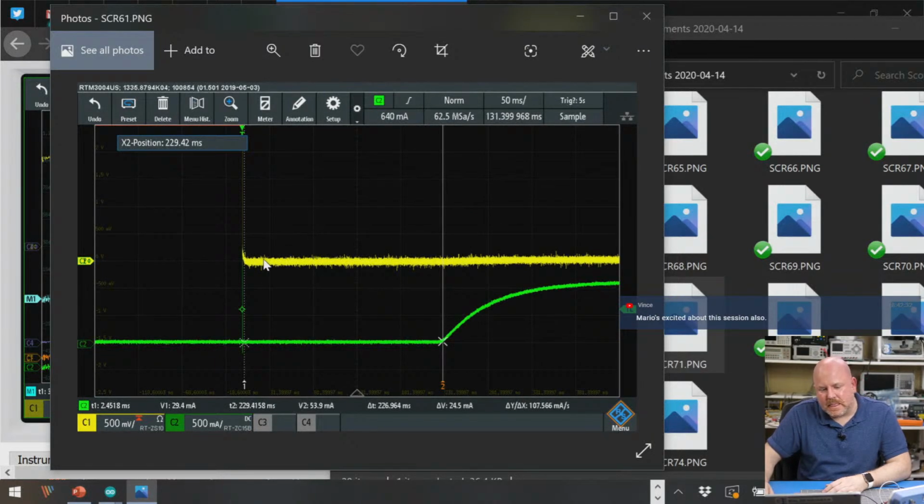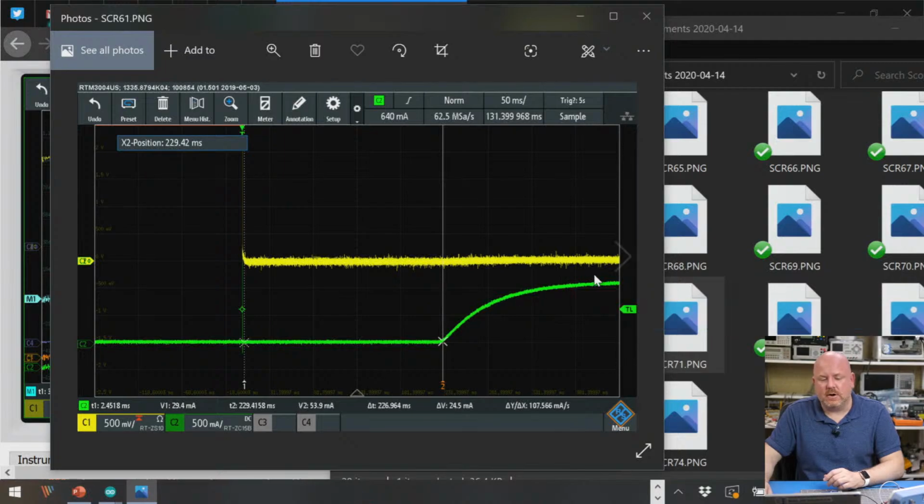is this screenshot. This is when the transistor turns on, and you can't see it because the cursor's in the way, but there was a little glitch happening. When the transistor would first turn on, the load would be super low impedance. It would actually show a current of like 10 amps for a couple of nanoseconds, and then 250 milliseconds later, it would turn on correctly. This delay was driving me insane because I couldn't figure out what was happening, which is why I switched to a traditional resistor, because it was completely screwing with what I thought was happening. So, fun times.